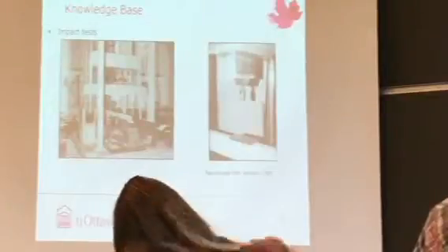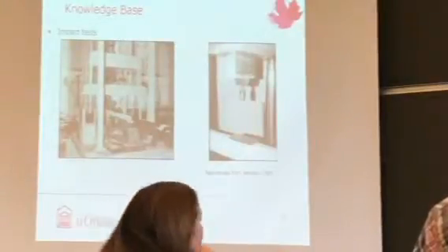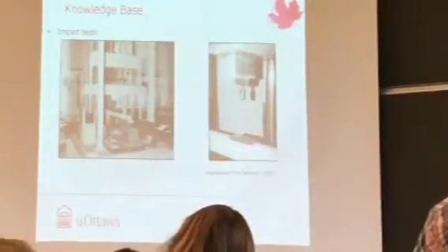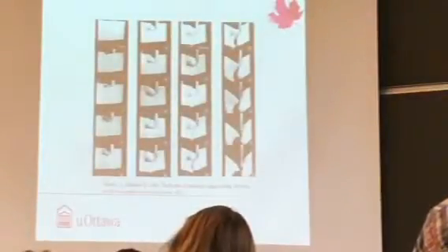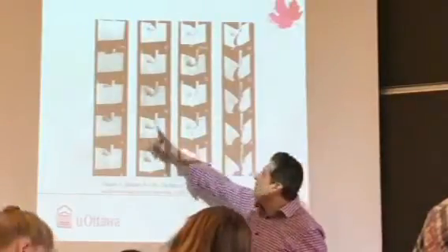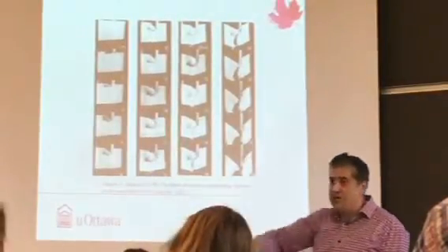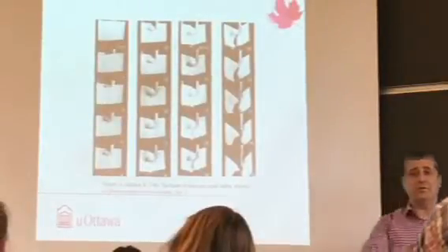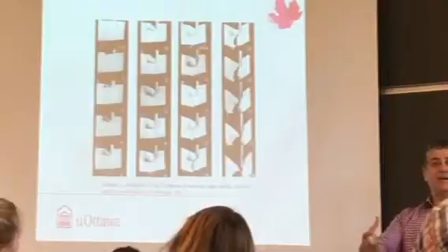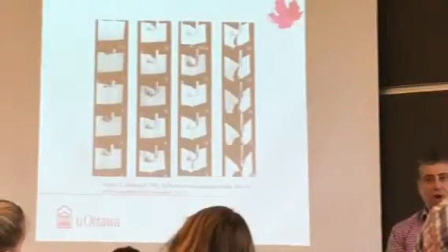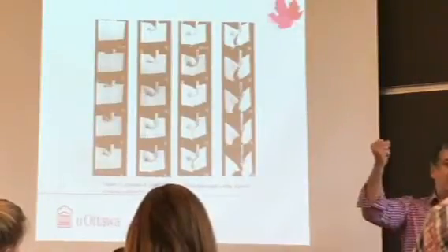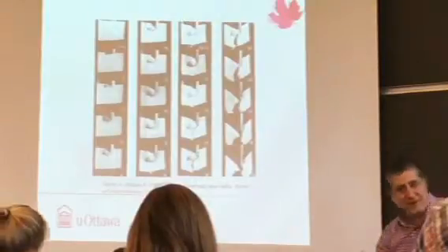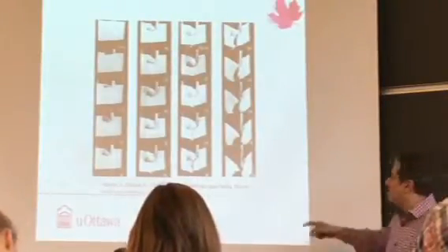Impact is not exactly the same as blast. It's not in the same range of strain rate, for example, so one has to be careful translating information. But what we saw from the literature is that you take whatever piece you have and hit it very, very fast. If you have a beam, you could take a very large mass and drop it, and because it has a large mass, the impact is going to be very fast, or you take a small mass and go with higher speed. So it's either the acceleration that you increase or the mass that you increase. Bottom line is, you see how it broke like this.